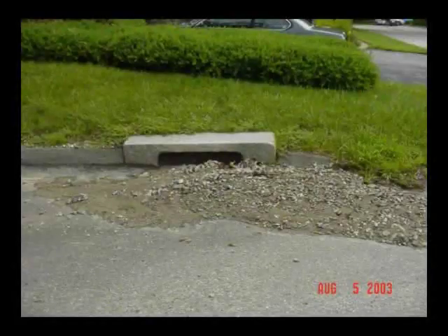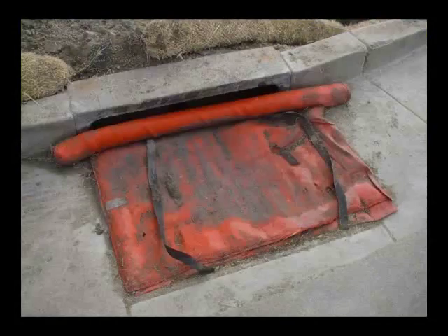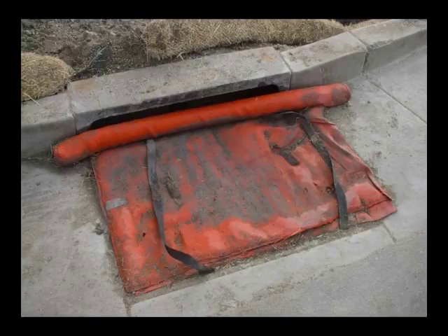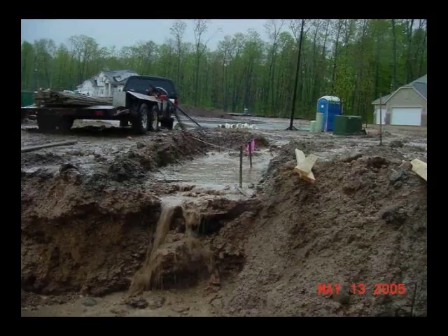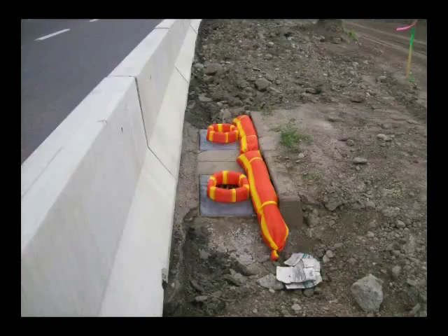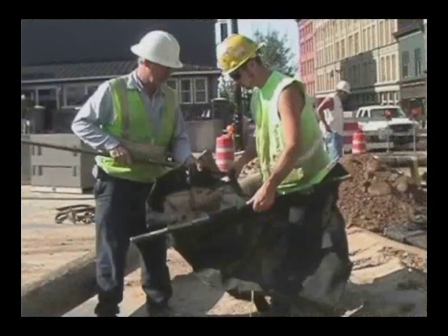There are several methods of inlet protection. Inlets can be sealed with an impervious material if runoff can be contained on site. However, on most construction sites, it is necessary to discharge stormwater even during construction. On reconstruction sites, it is important to protect both the existing and newly installed storm sewer. Let's discuss a few ways to protect storm sewer inlets on construction sites.